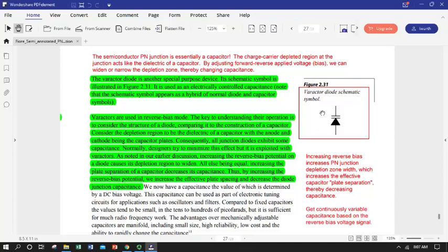And so we can still pass an AC signal, but we superimpose that AC signal over the DC bias that literally sets the capacitance we need. We might still have a rectifying effect as we try to go backwards on one half of the cycle, but then we can just use two in tandem to overcome that.